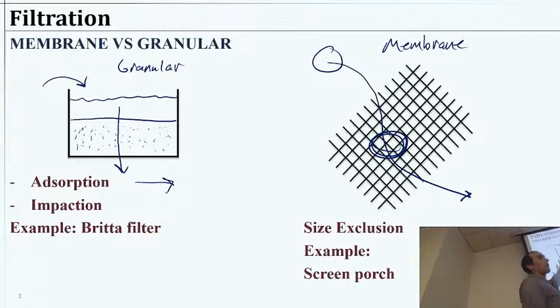The important thing here is with granular filtration, you can actually have a particle that's really small compared to the pore size between the grains, and you bump into something. Well, if you're sticky, then you're now stuck to that wall. So even if you were able to navigate a little corridor, maybe you run into another particle and stick, and then you're too big together, or maybe you just bump into the wall and you get stuck. Okay, so that's kind of what's happening in the granular filtration case. A good example of this would be your Brita filter.